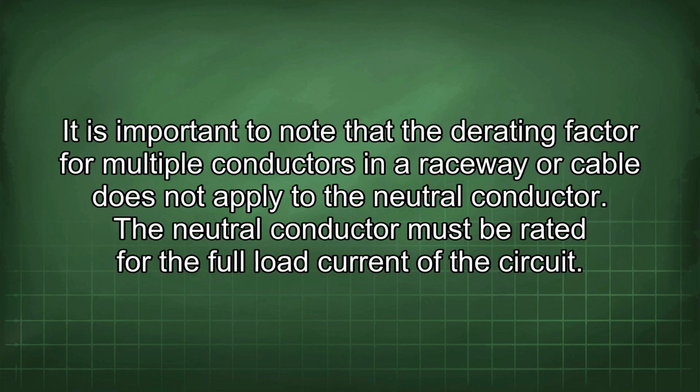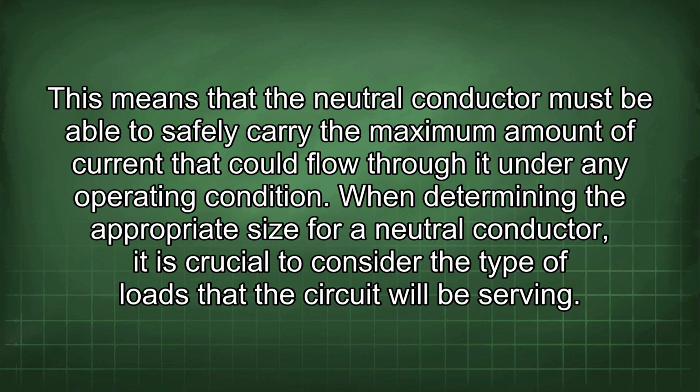It is important to note that the derating factor for multiple conductors in a raceway or cable does not apply to the neutral conductor. The neutral conductor must be rated for the full load current of the circuit. This means that the neutral conductor must be able to safely carry the maximum amount of current that could flow through it under any operating condition.